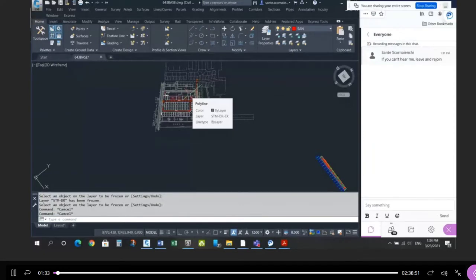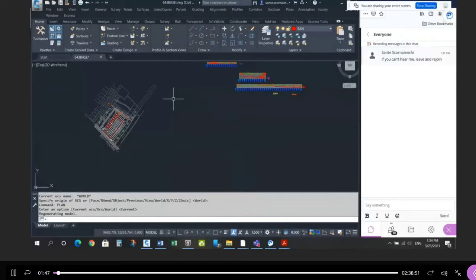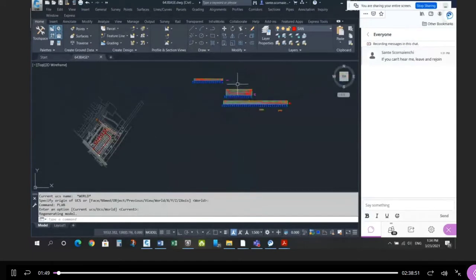So the way I marked this is I had to first look at the road design, right? So I'm going to go back to the UCS plan. And if you look at the first 4 lines of the marking rubric that you received by email, you'll see I had some key station locations and some key elevations I was looking for. So if your horizontal alignment was correct, and that should have been correct or corrected after the first submission, and you followed along with what I did in the video or in class, then you'll see some key intersection and key location elevations.